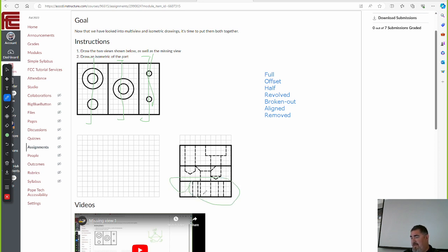This one would be this hole, that line, and that line. And that one would just be this line up here and those two, right? So they wouldn't be stacked on top of each other. Because you get everything beyond the section, you don't use hidden lines for. So now you can see just that section and beyond, and this view that's pretty muddy becomes a little bit clearer. Yes, you get more views, but if you need those views for the clarity to see what's actually going on, then it's beneficial.